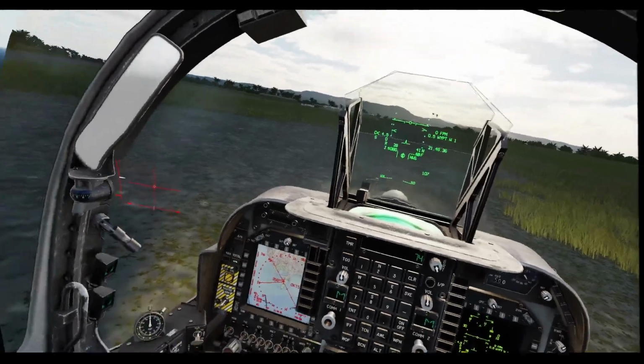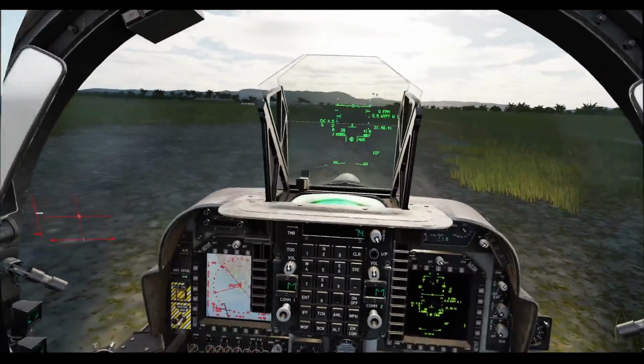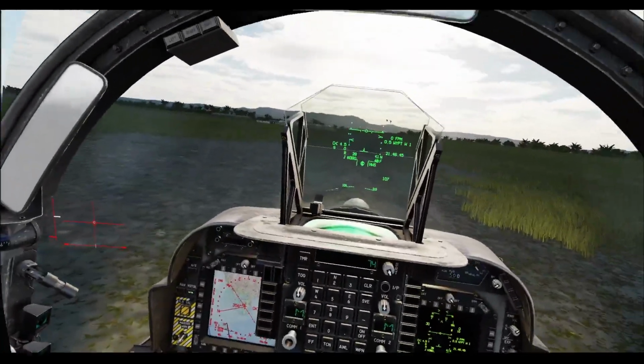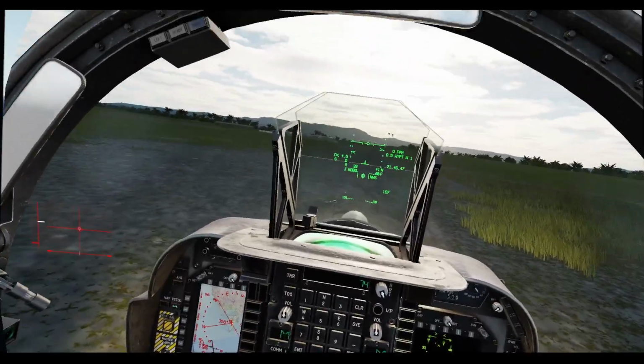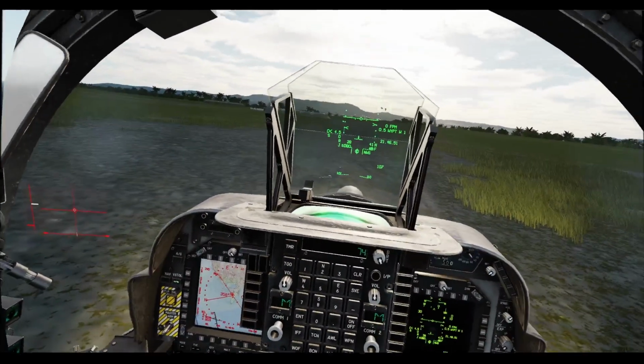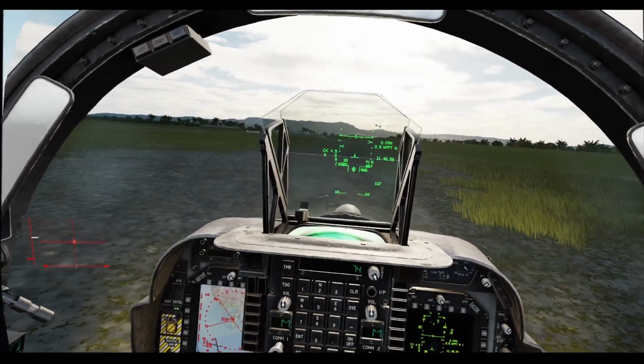Especially in high crosswinds, really important to do proper positive nozzle braking. Do not use nose wheel steering in any way, just use the rudder. Once you're slow enough, engage the nose wheel steering using only the nose wheel steering button after you've centralized the rudders. Once you feel that the aircraft's under control, then move the anti-skid switch back to the nose wheel steering position.